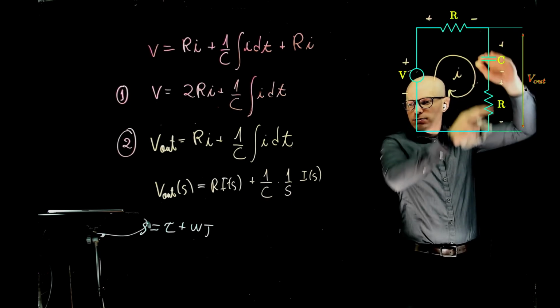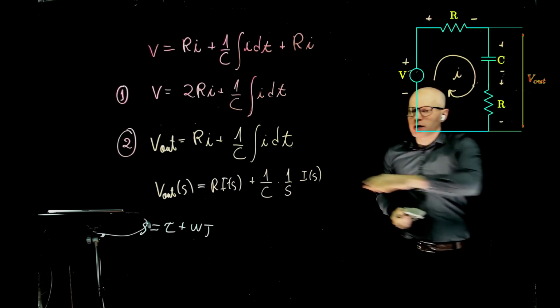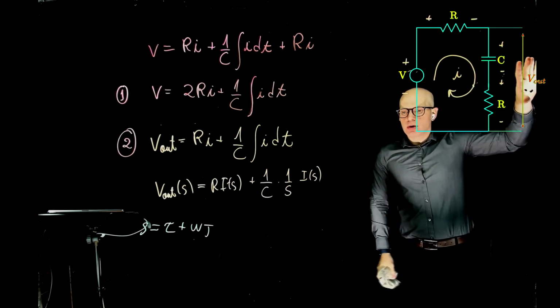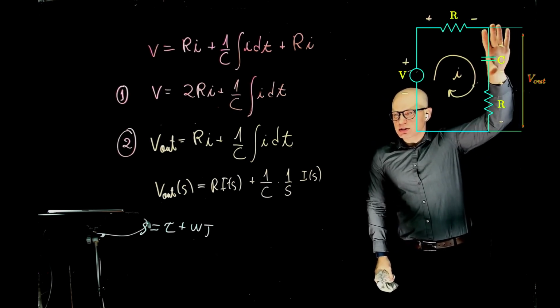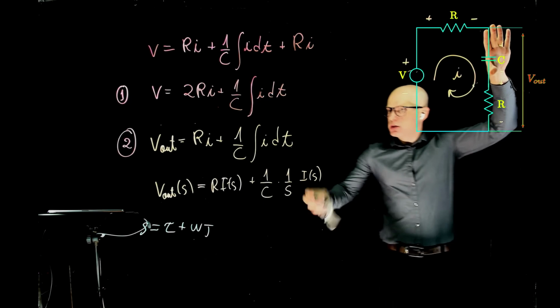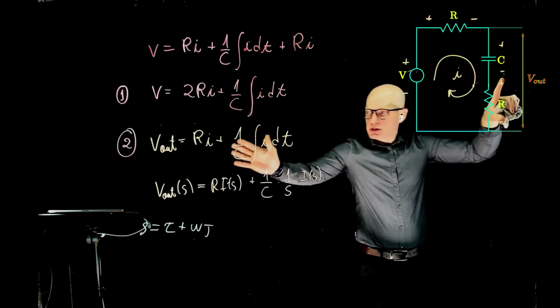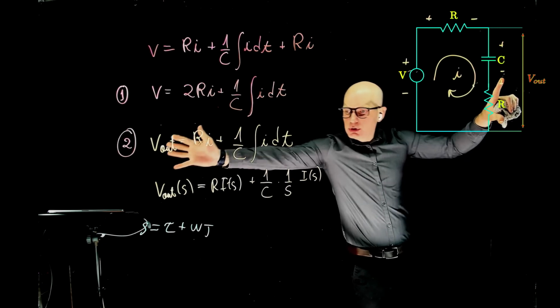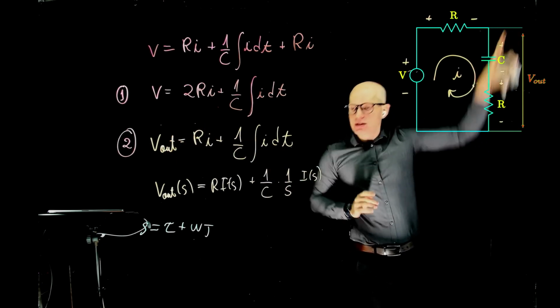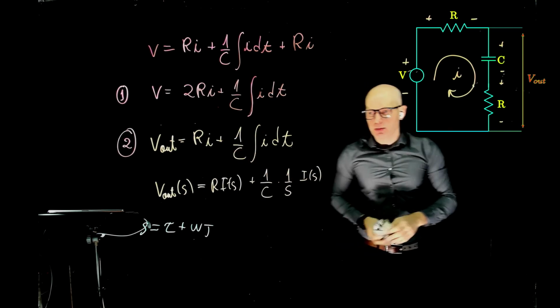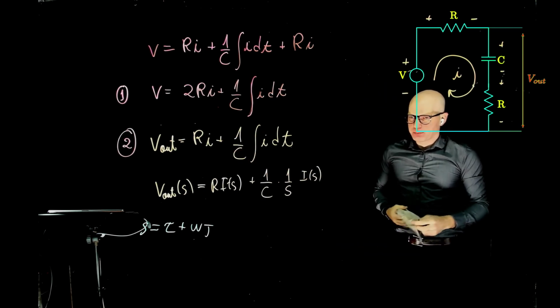So that plus that, that's why we have the summation over here. If the voltage drop was only defined across C, it would just be this part of the equation. If it was only defined across R, this would be the solution only. But because it's both and they are in series like that, we can simply add them up. Okay, thank you.